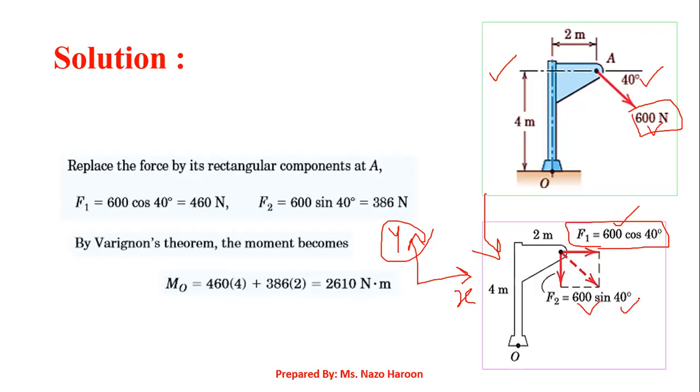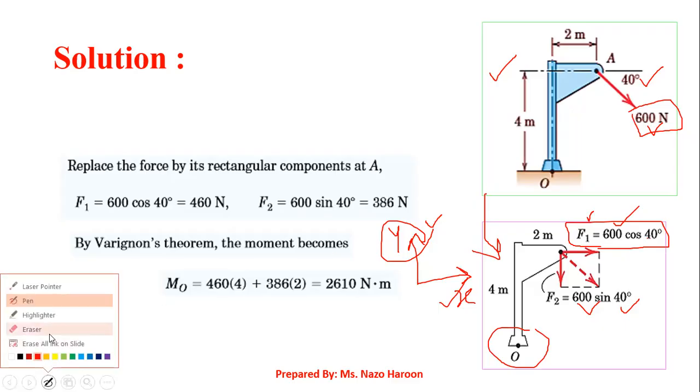So now you have the forces along both of the axes, x-axis and y-axis. What else you need in order to find the moment is the moment arm, right? Now you have two components, so ultimately you have to multiply these two components with two moment arms in order to find out the cumulative impact of the force about this point O, to find out the moment. So let's start solving for this. Let me first raise all this so that I can explain with more comfort.